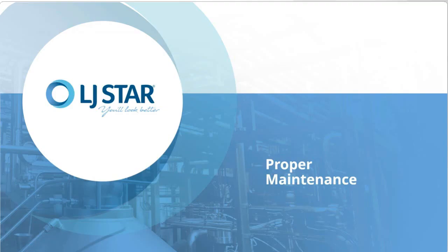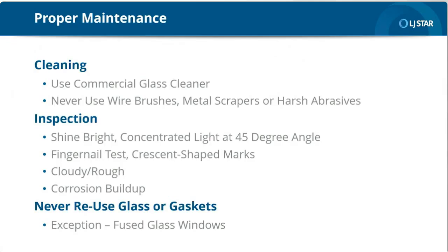We have covered all the considerations of sight glass selection, but what about the day-to-day work that preserves your investment? Like other process equipment, sight glasses must be maintained properly to maximize their life and your return on investment. Also, in applications involving high pressure and high temperature, the proper care and inspection of sight glasses are critical to workers' safety. When glass under pressure fails catastrophically, shards travel at ballistic speeds.